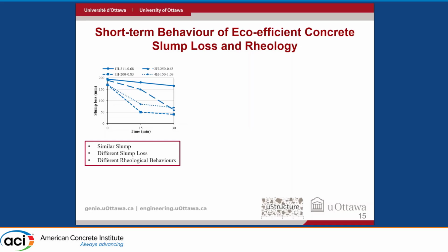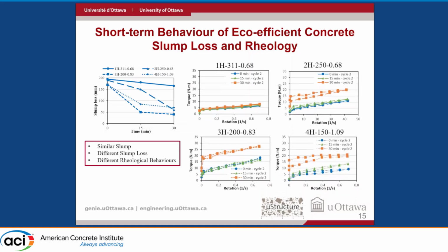Another thing that we realized is that normally people characterize workability of concrete in a global way just based on the slump, and there are several colleagues who are rheology experts trying to fight to get the thing properly discussed. So you see, we have more or less the same initial slumps, but we have very different rheological behaviors of the mixture.